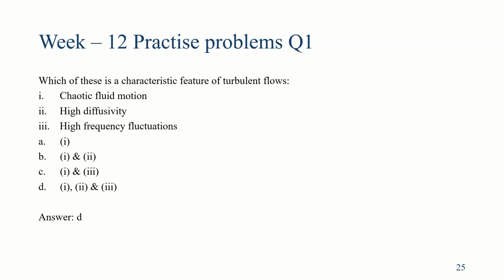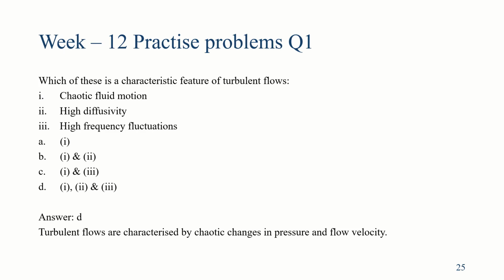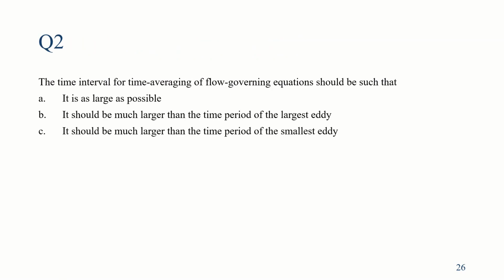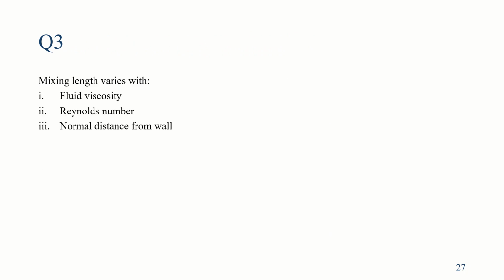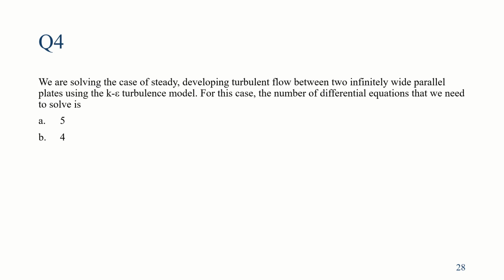In week 12 also we have seen the practice problems, non-graded assignment problems, where we have dealt with turbulent flows. It means that it has chaotic fluid motion, high diffusivity, and high frequency fluctuations. The time interval should be larger than the time period of the largest eddy formation, and mixing length varies with normal distance from the wall, where we say Prandtl's mixing length is the distance a fluid particle travels before it gets mixed with the surrounding particles. The fourth one is about the number of equations.